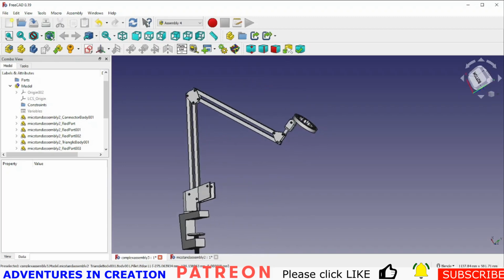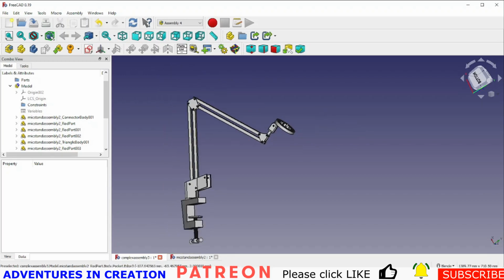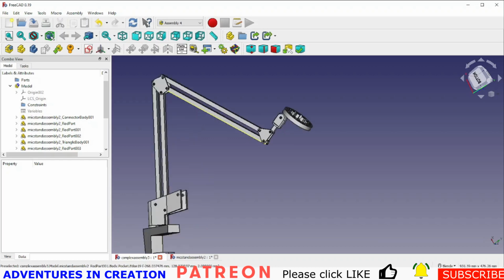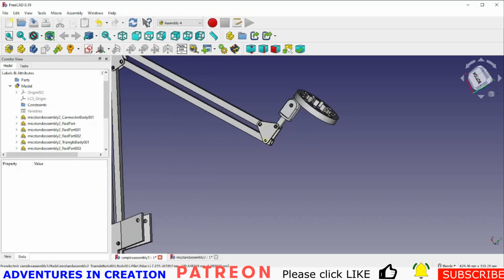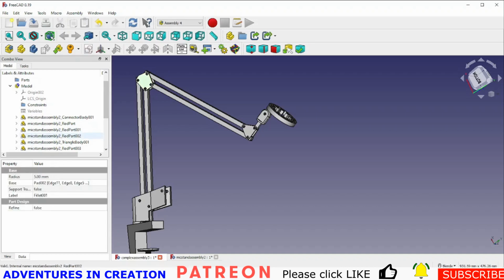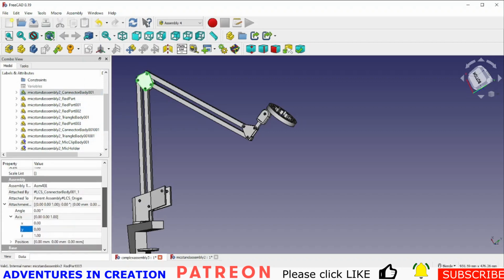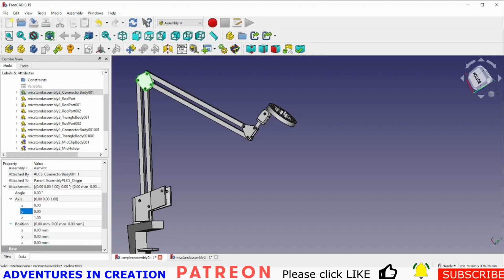So I know some of you guys don't like to use a second piece of software. So that's why I've showed you how to do it here in Assembly 4. I literally just went in, set up my LCSs to all the holes, and then connected it by those LCSs. And if it required an offset, I just offset it. And you can change those offsets. So if I select that part in here, that is a connector body. So if I select that connector body, you'll see here I can do all the offsets right here. So if I needed to offset it, I could offset it from here.